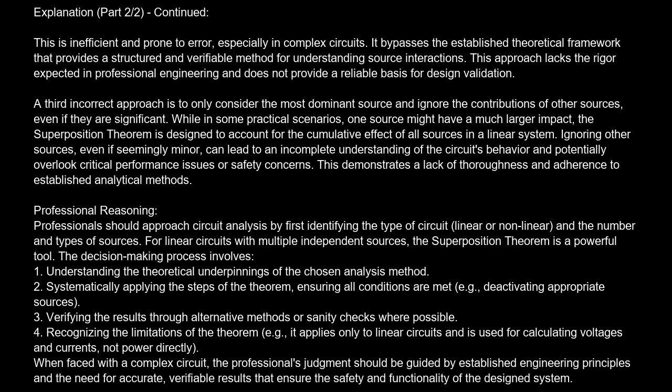Professional reasoning. Professionals should approach circuit analysis by first identifying the type of circuit, linear or non-linear, and the number and types of sources. For linear circuits with multiple independent sources, the superposition theorem is a powerful tool. The decision-making process involves 1. Understanding the theoretical underpinnings of the chosen analysis method. 2. Systematically applying the steps of the theorem, ensuring all conditions are met, e.g., deactivating appropriate sources. 3. Verifying the results through alternative methods or sanity checks where possible. 4. Recognizing the limitations of the theorem, e.g., it applies only to linear circuits and is used for calculating voltages and currents, not power directly.